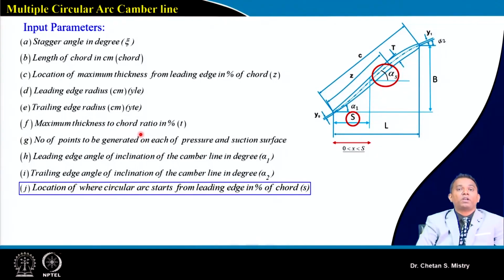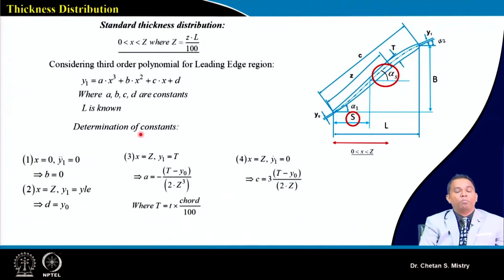So as per how we want to manage our flow on the suction surface of our blade, we need to modify or make the aerofoil, or make our camber line. Once we are ready with our camber line, the very next question is how do we put in our thickness. So let's move towards the distribution of the thickness.